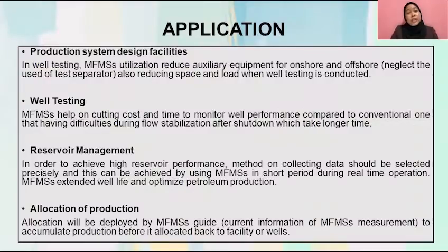Okay, we go to the application of multi-phase flow meter. For the first one is production system design facilities. The use of MFM can reduce hardware needed on onshore, offshore topside and also offshore subsea application. And the most important thing is the removal of dedicated test separator for well testing application. Thus, use of MFM for the topside application can reduce load requirement and also reduce platform space.